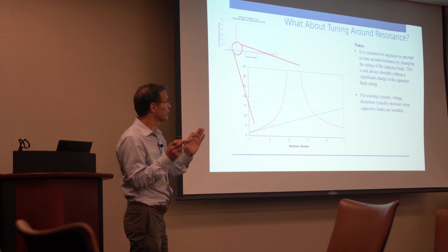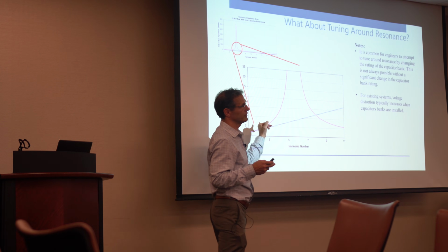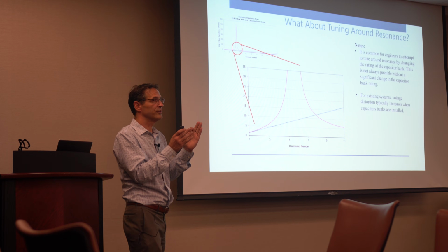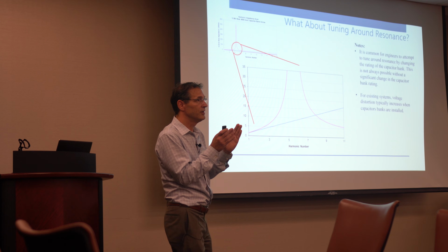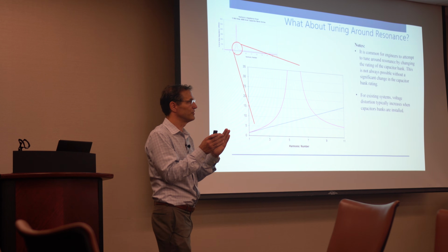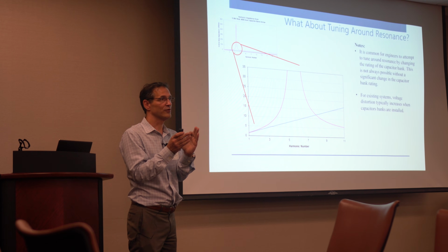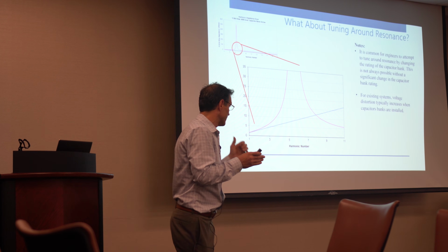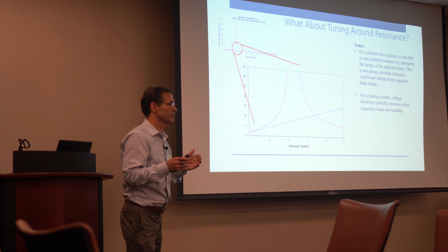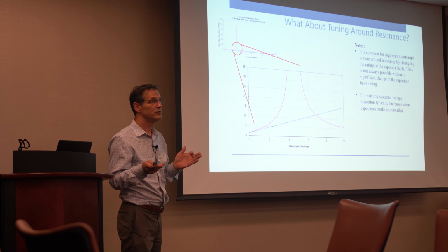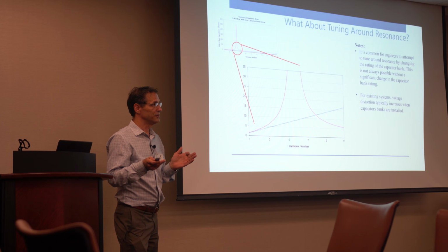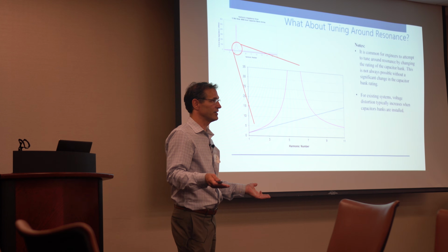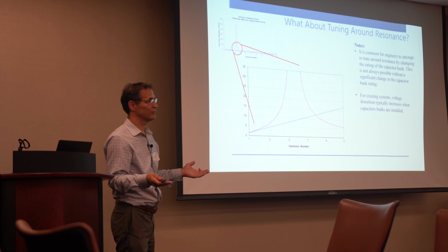The next question really is, how accurately do you know this? And that's what we get into. How it's going to move, it can move around, right? When a utility calls and tells you their short circuit level, how much can you trust that level of short circuit current they gave you? A good point is if you live in Kentucky where there was a lot of coal generation, the old administration comes in, they shut those power plants down, and the short circuit level changes in that area. So you can't trust that the short circuit level is going to stay the same.